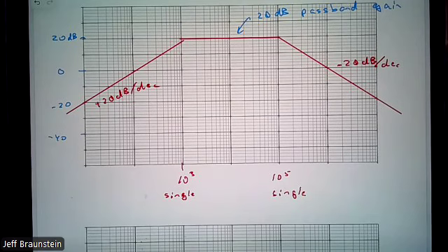So if I gave you the exercise, and I did give you this in the homework, so I'm kind of setting the stage for you to get ahead there. What do we want to do if the expectation is 40 dB here and 40 dB here? How are we going to build that? Yeah. So double poles are not quite, I mean, we've got to be careful. We do need a double pole, but I want to be a little bit more specific. Yeah, another RLC circuit, but again, 40 dB and 40 dB. So how do I get 40 dB if I think of just a low pass filter?